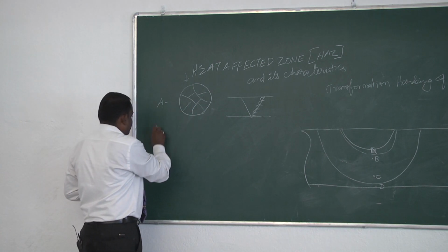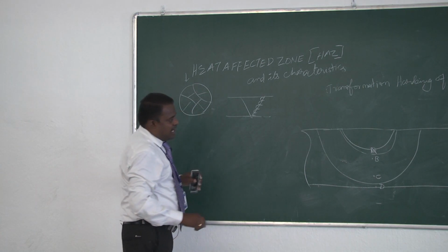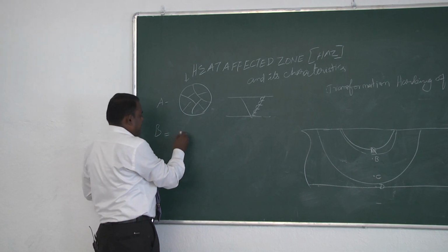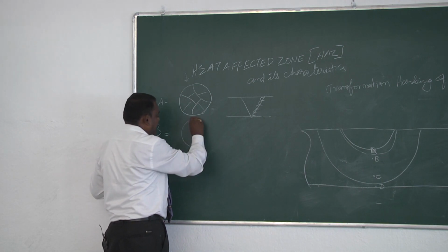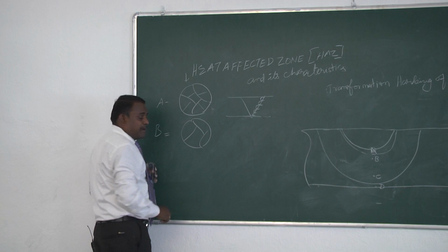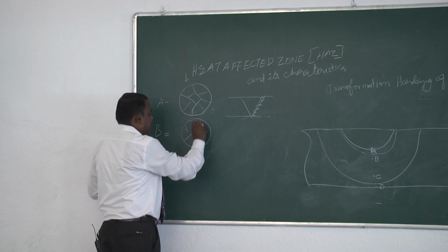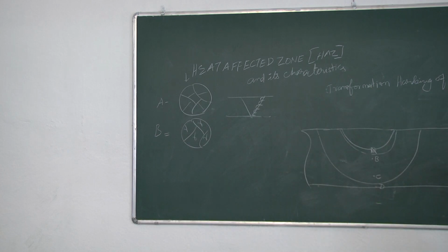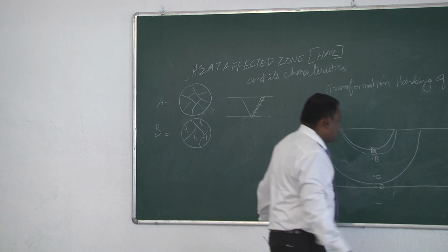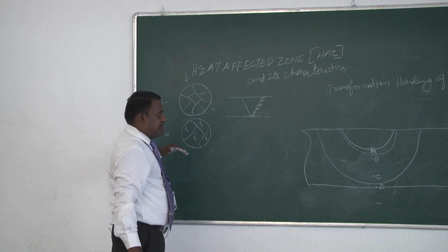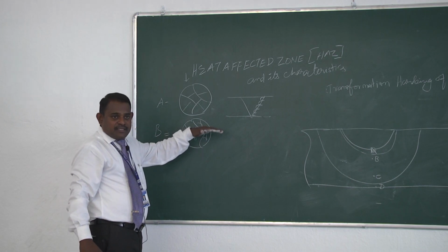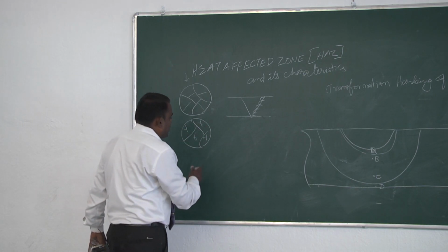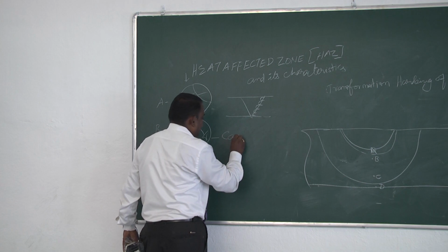And coming to location B, it will be above A3 temperature, so it will have a complete gamma structure. All of it is gamma. Then when it is cooled to room temperature, gamma has to transform into alpha and Fe3C. But at the same time, that is a very high temperature over a long range of time. That is the reason why we only have a coarse grain microstructure.